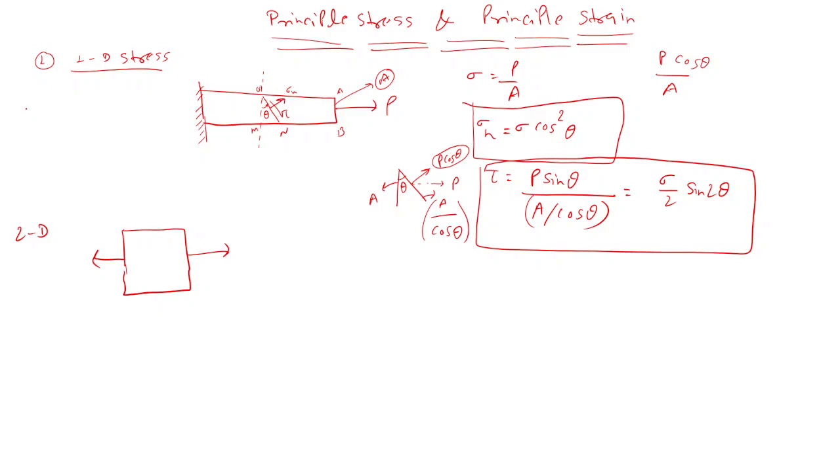So one thing you must remember is the direction of theta, and the second thing is the direction of tau, tau xy we can say. That we will see when we put in shear stress; at that time I will tell again, so that's why I haven't told. So this theta you keep in mind: if you are taking the anti-clockwise direction, then you have to take it as positive, in all formulas whatever we are writing here.